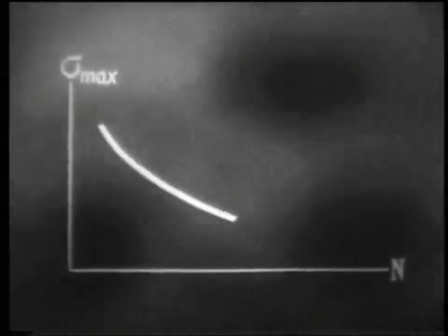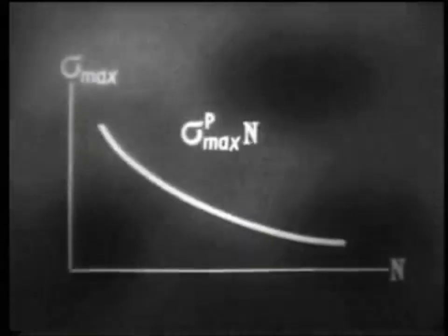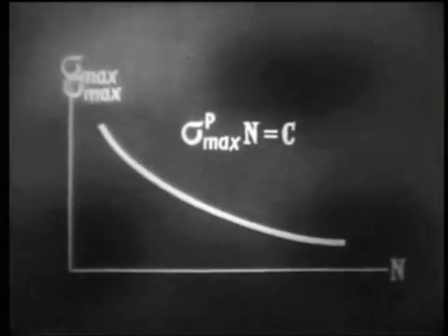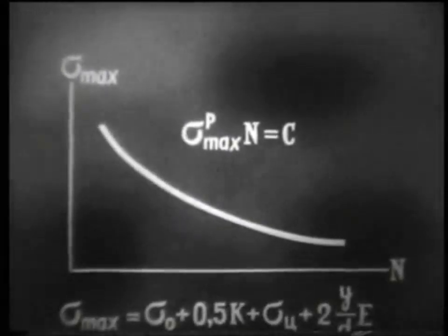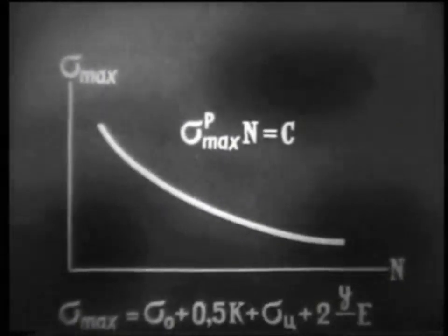The durability of the belt is limited by fatigue damage caused by alternating stresses. The experimentally obtained fatigue curve reflects the dependence of the number of cycles to failure on the maximum stress. Durability decreases dramatically with a decrease in the diameter of the pulley and an increase in belt tension. Therefore, it is preferable to use an automatic tensioner that provides the minimum required value.